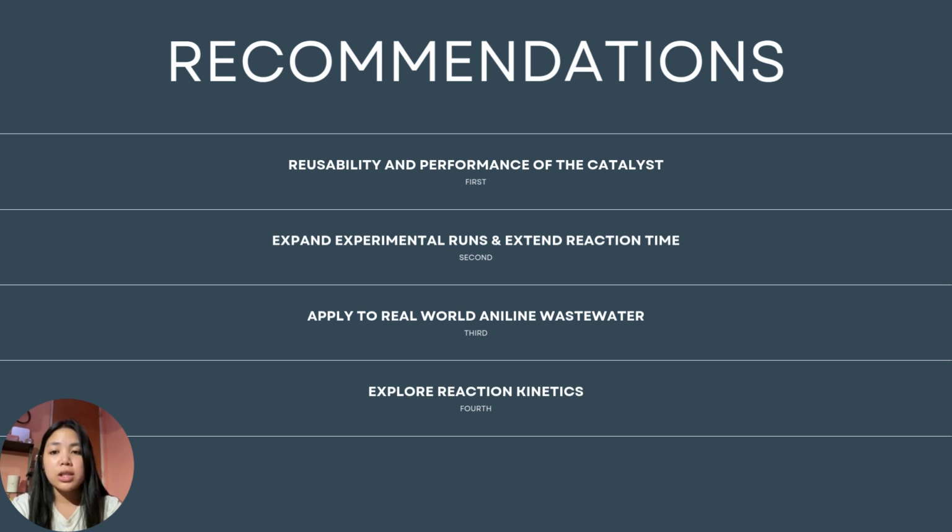We also suggest expanding the parameter ranges, especially for pH and catalyst dosage, to better understand the degradation limits. Our treatment duration was fixed at 30 minutes, which might not have been enough to reach the full degradation potential. Longer treatment times could improve efficiency even further. We also recommend applying this process to actual industrial wastewater containing multiple contaminants. Real wastewater contains various organic and inorganic compounds that could affect aniline degradation.